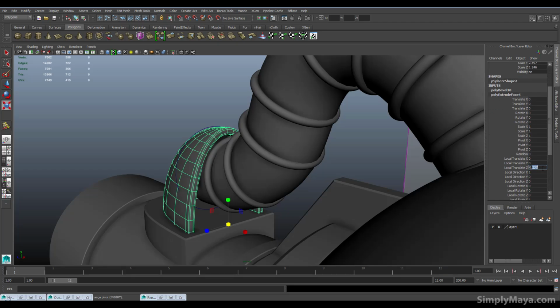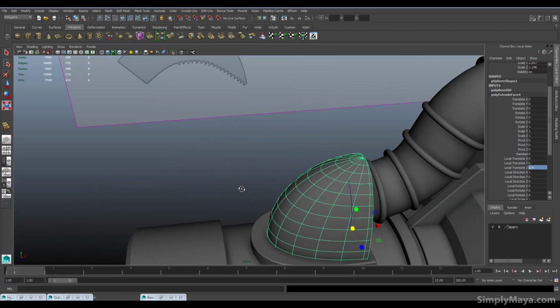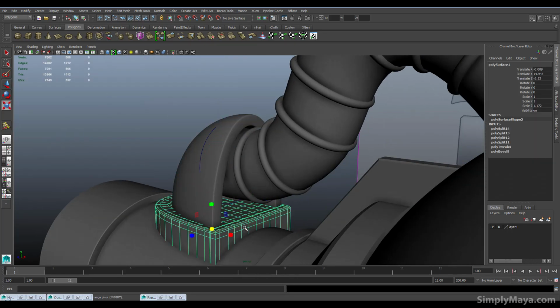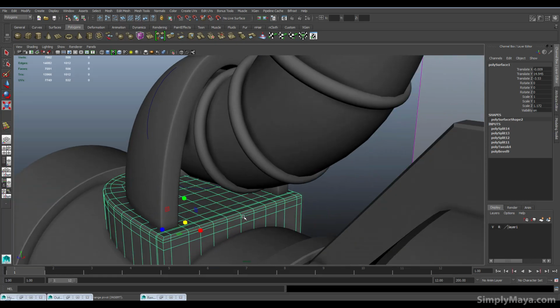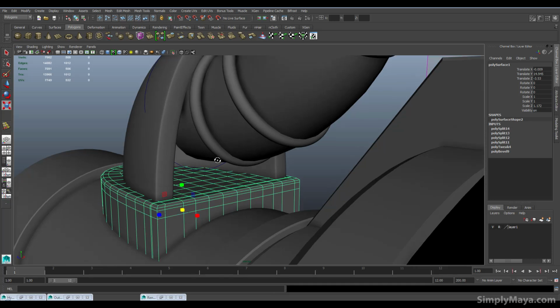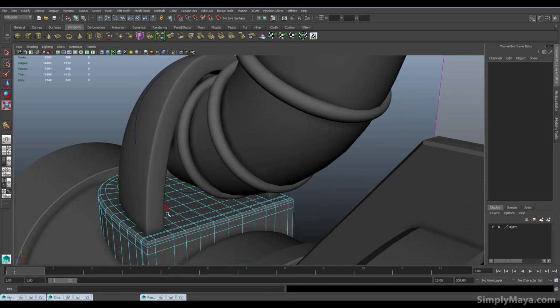go down to the extrude in Z and change that to maybe 0.4, and you'll see that it grows outwards. So that seems about perfect to me. Done. Now I want to also make sure that my thing along the bottom here also comes up to meet the pipe. So I'm just going to go into face mode and select a few faces.